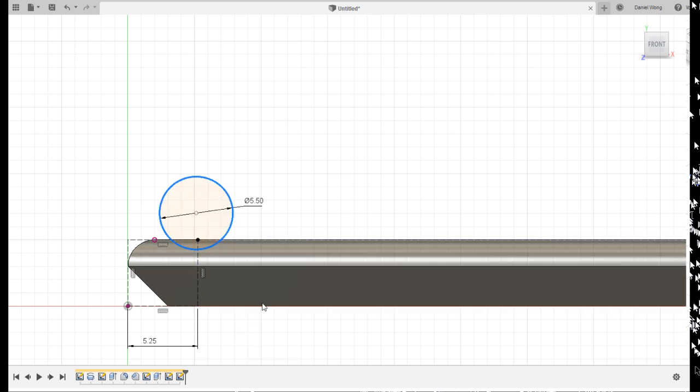That's quite easy to do. We can draw another line that goes straight up, and dimension this with a length of 4.5. I'm going to convert that to a construction line because we're not worried about that, and put the center of my circle on that. You notice that's not touching just yet.